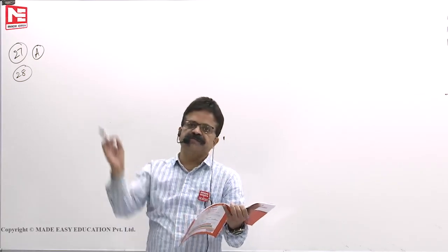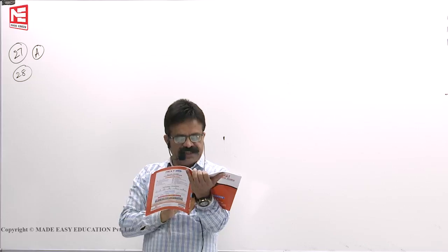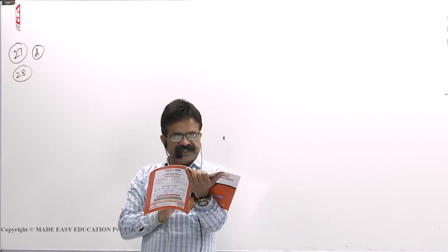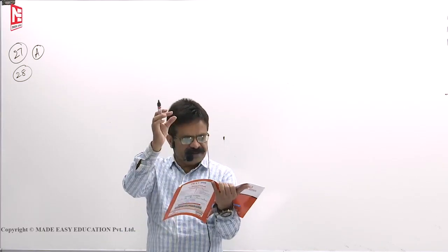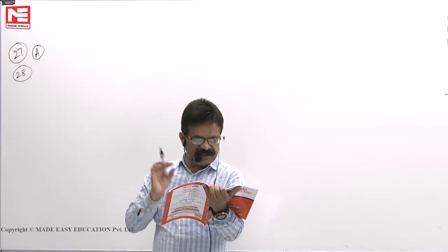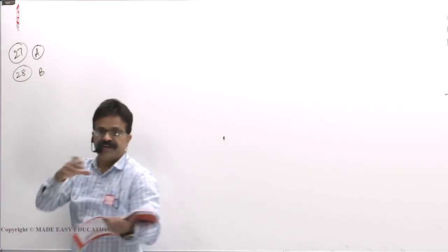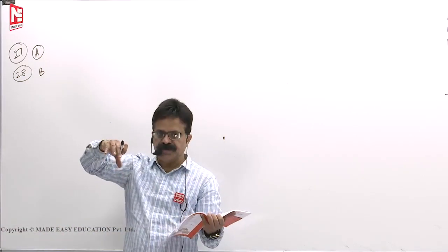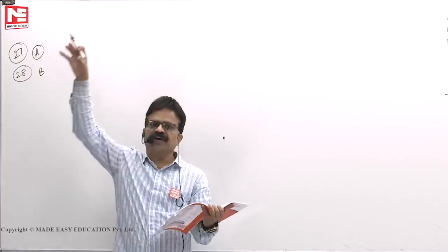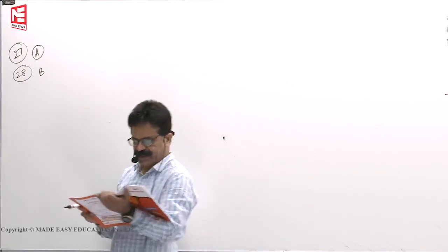Without the load, the arch will hog, so negative bending moment should be there. You see here option B, from A to center there was a positive bending moment, then there is a point of contraflexure and negative bending moment came. That's all. B is the option. Where you are pressing it will sag, positive bending moment. Where you are not pressing it will hog. So it goes up, that's all. No great thinking is required for that.